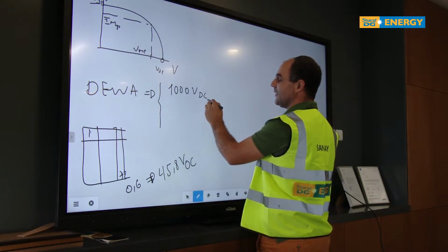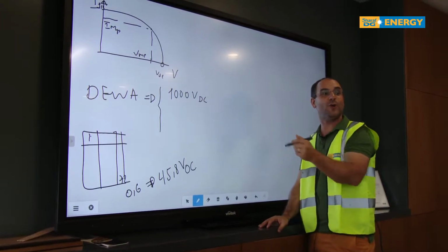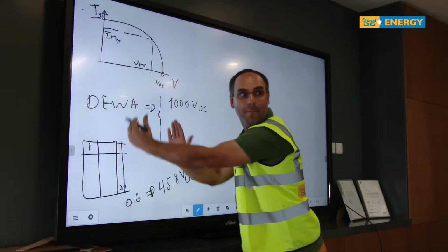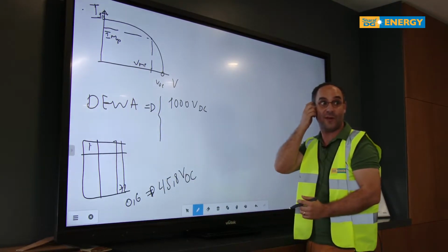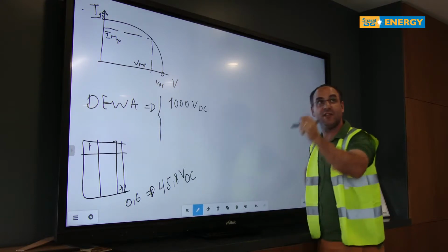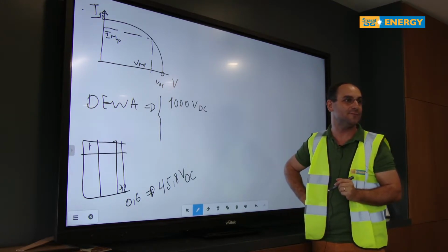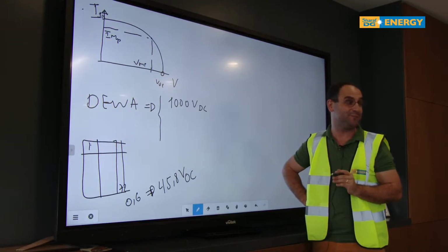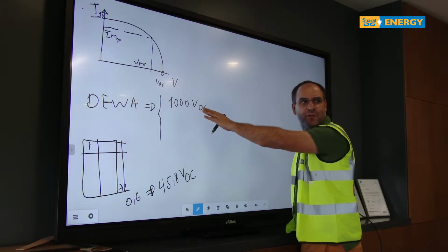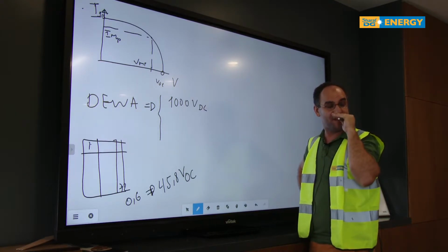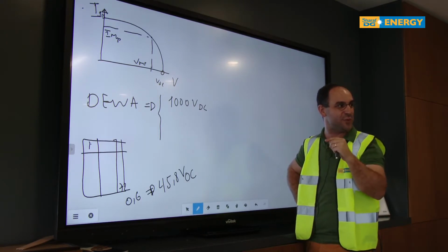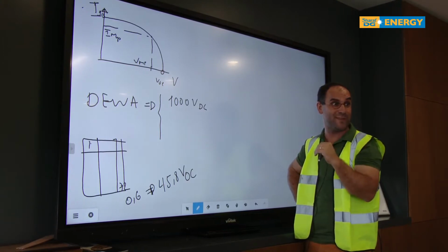So we as solar industry people, we also do the same exercise, but we don't do it at the cell level. We do it at the module, solar module level, okay? So we know that we cannot show to DIWA that your system is 1300 volt. We cannot do that. DIWA has other restrictions, but the more important thing for you to understand is this one is just the standard, to make sure that your solar system in this project does not cross 1000 volts.